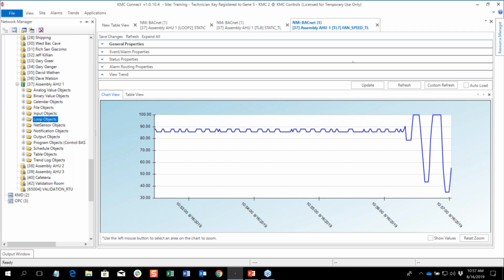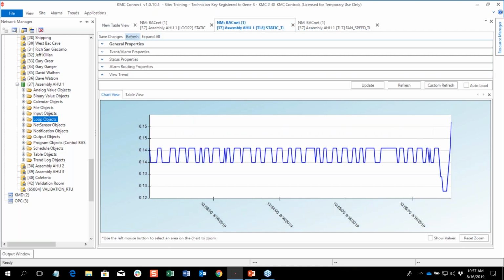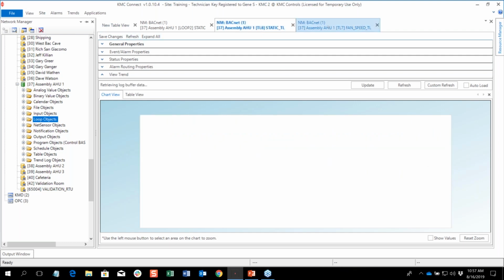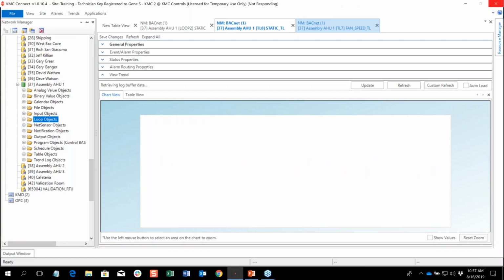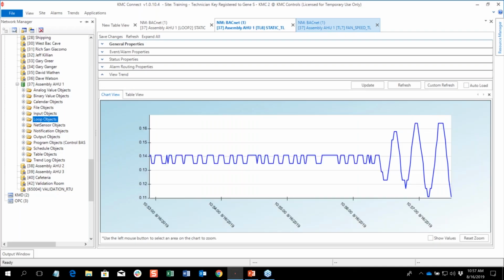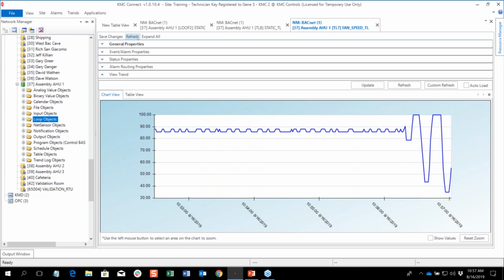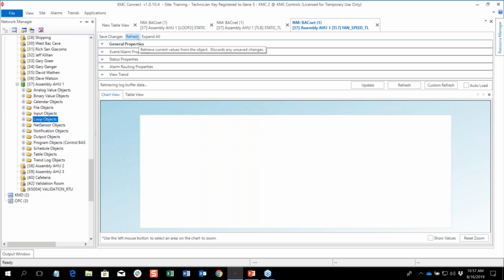Since you've decreased that proportional constant, it would take less air to produce the same response. So that proportional term is moving faster now with 0.05 in there than it was with 0.25. Yes, that's what's leading to our oscillation. As you can see, this is a pretty low pressure system, but it should give you an idea of what's happening when we go to tune a PID loop.